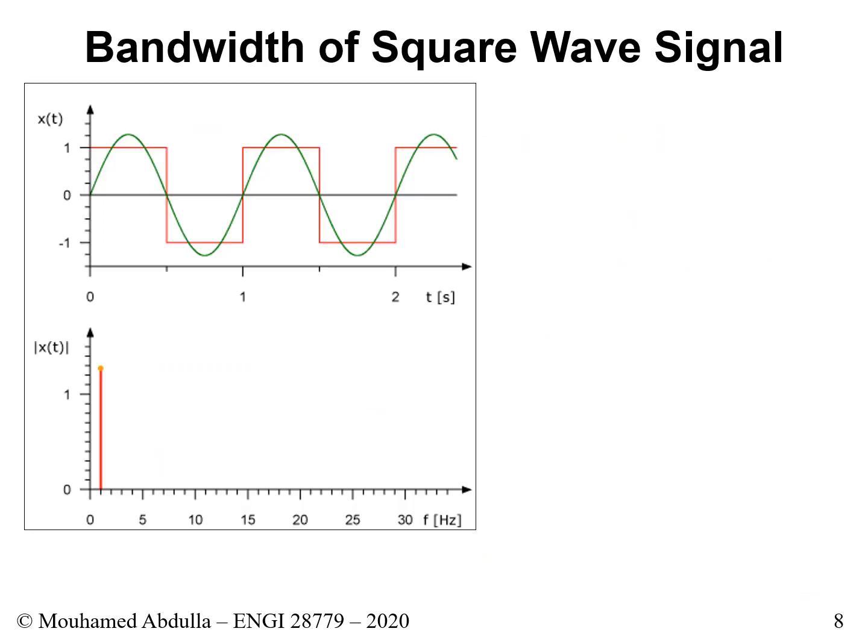So just to recap, so far what we've seen is we've taken a periodic signal, and we said to ourselves, let's just consider the square wave signal. We looked at the square wave signal, we got its general characteristics in the time domain. Then we represented this square wave signal using Fourier series techniques, and we were able to represent the square signals with an addition of multiple sinusoidals. And this was done in the time domain.